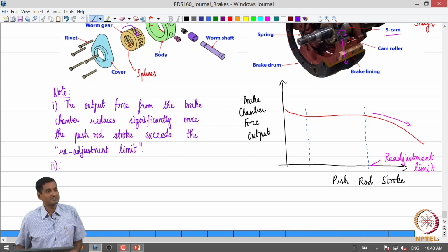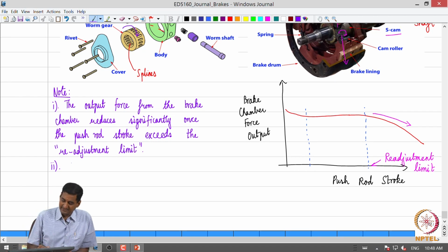In an air brake system, the human effort does not pressurize the operating medium. Consequently, the tactile or sensory feedback available to the driver in the presence of a leak in an air brake system is smaller, and that makes it a challenge for human beings to detect leaks. Okay, so that is another challenge with air brake systems.